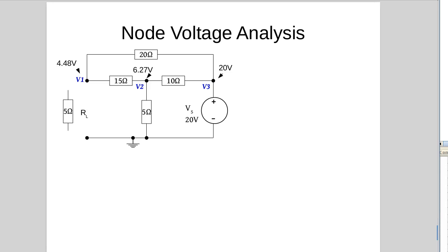Well, if we take that resistor out, we could actually look at that and consider that a power supply and analyze it using a Thevenin or Norton equivalency. So if we built a Thevenin equivalent and analysed that, the short circuit current would be 1.3636 amps. If we found the open circuit voltage, it would turn out to be 13.0435 volts. And the internal resistance, or the Thevenin equivalent resistance, would be 9.5655 ohms. So you might want to pause the video and write those numbers down.